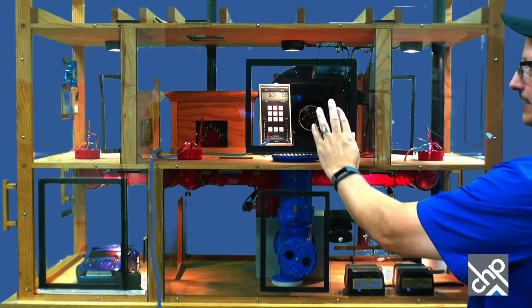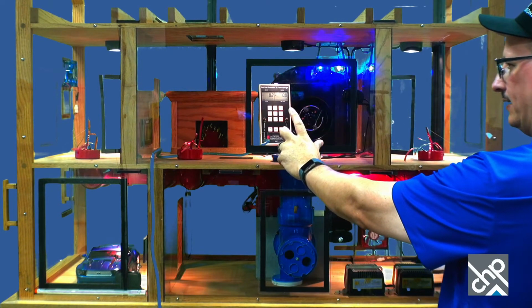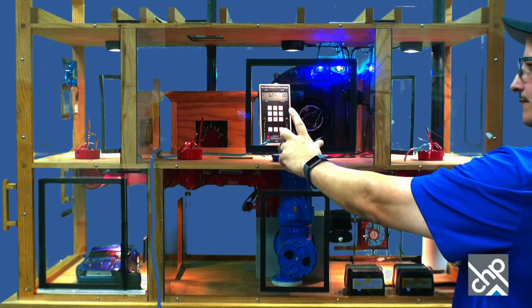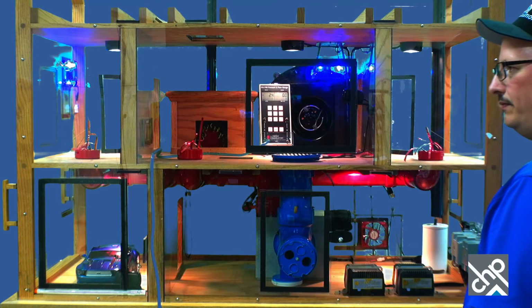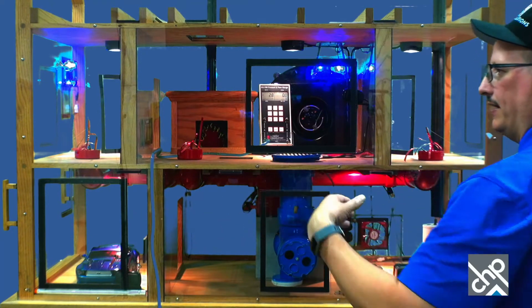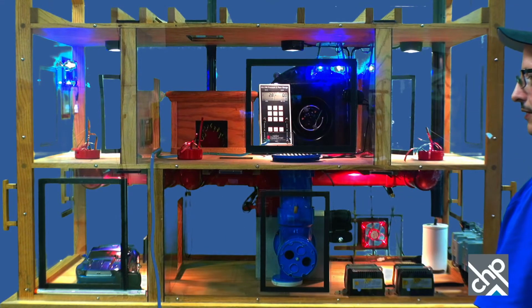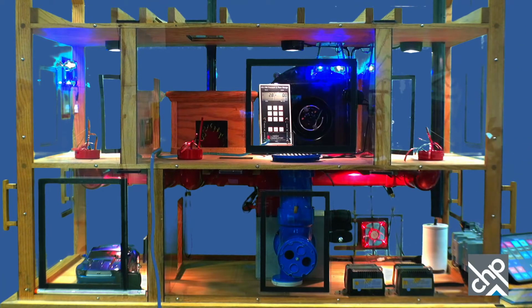So if I turn on the kitchen fan here, I'm going to turn just the kitchen fan on, and let's see if it changes it a little bit. And then I'm going to turn the bathroom fan on, which is over here. Changes it a little more. And then the dryer. Again, we're measuring pressure from here compared to outside. The dryer, we're going to turn that on here. And the dryer is all the way in the basement. Let's see if it affects anything. I'm going to turn it off and back on just so we can see that one again. It did change a little, went from 2.8 to 2.9. And then I'll turn all of them back off.